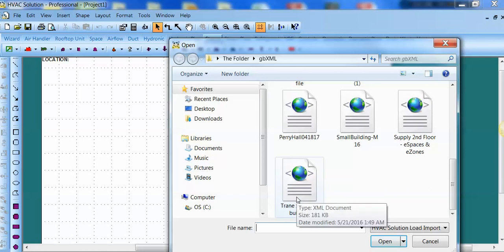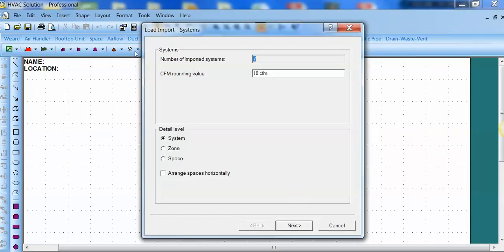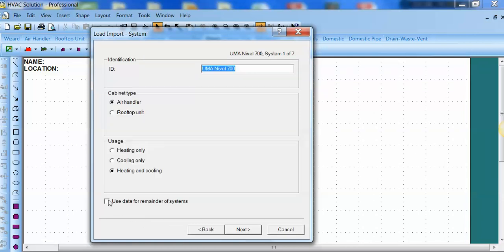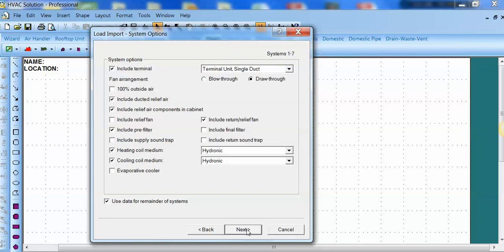This is the spatial data, the zoning, and the heating and cooling loads for a 35-story building in Central America, in Panama City, Panama. I open the file, and it opens the gbXML wizard inside the software. It's going to take that data and populate the wizard with the default information. I'm going to leave the default in the interest of time, but you can change anything in the white boxes. This building is divided into 7 zones. So we're just going to click next, and you can see the layout of the information.